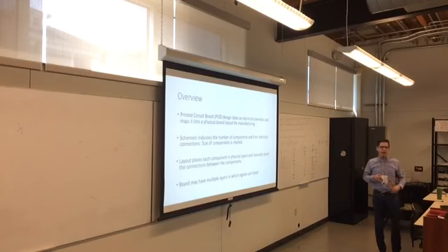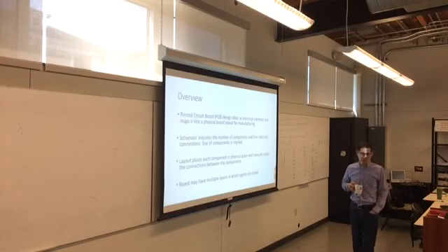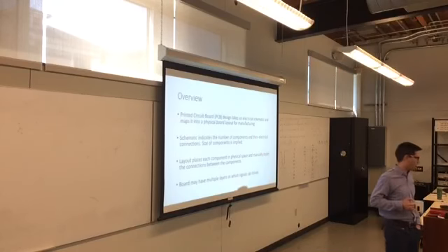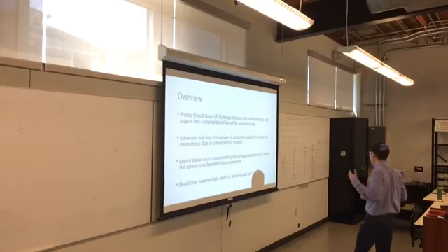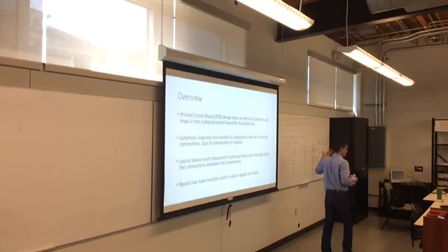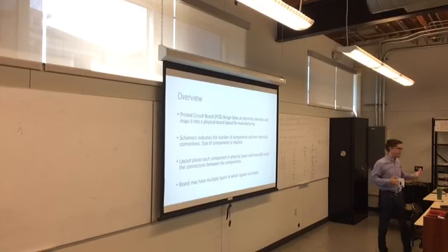Generally, you manually route all of the layout, and you do it because auto routers are stupid. We'll look at auto routers in an assignment and see how they work. The board can have multiple layers. So there can be a top layer, a middle layer, a bottom layer, so you can sort of have like three floors to route your signals through. So in a nutshell, PCB design is a schematic and it's a layout.